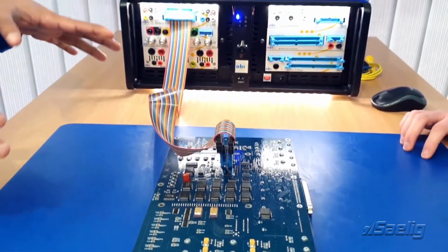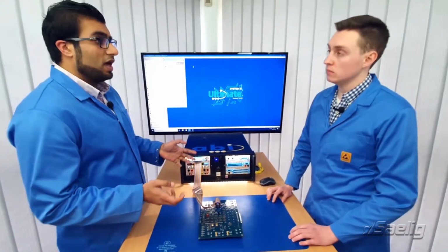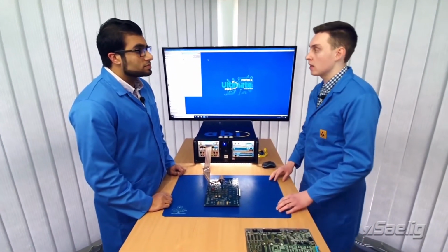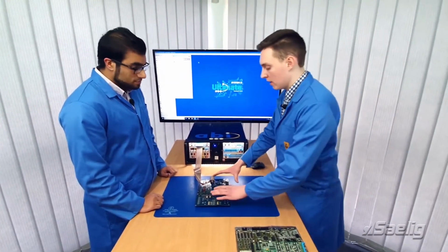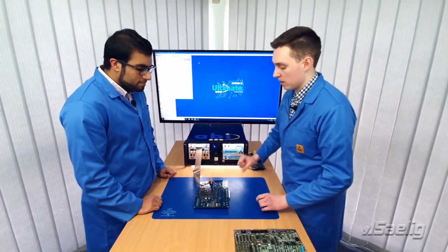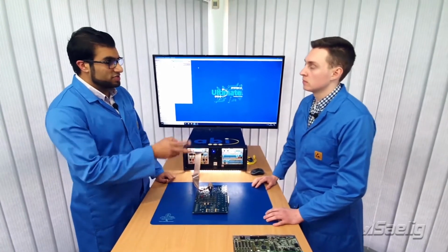So from what I'm understanding here, the traditional VI gives you a good idea what is going on around the device and the matrix within the device, is that right? Absolutely. So if you just did the 3D VI on an IC like we did in the last episode, you'd get to see everything outside that IC, but you'd leave a bit of a black spot within your PCB, and it's worth testing that with matrix VI. So it would be advisable to do both tests, would you say? Absolutely, to get that complete fault coverage.